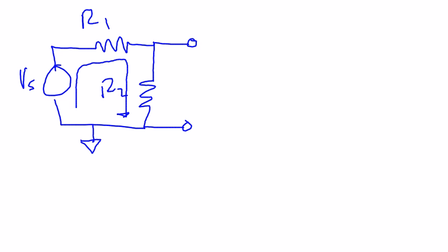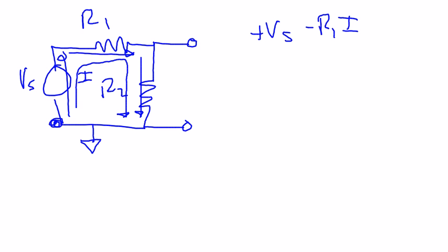And so a simple calculation of this can be derived by doing Kirchhoff's loop law, just starting right here and going clockwise by assuming a current I. We can start and say, all right, we're going to increase in voltage Vs, so plus Vs. We're going to go across the resistance R1, which is a voltage drop, so minus R1 times I, and down to another voltage drop, so minus R2 I, and that gets us back to our starting point, so that equals 0.